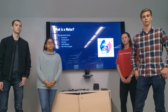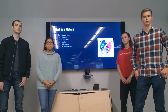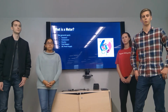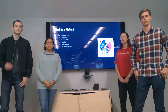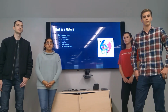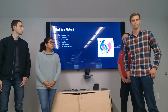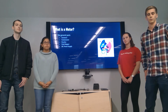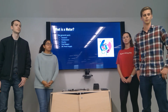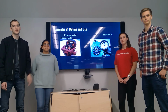The field magnets are typically, but not always, permanent magnets. A motor that uses permanent magnets will typically require less power than a motor that uses electromagnets as the field magnets. And the power supply, in the case of this motor here, is going to be a DC power supply, but some motors will actually use multi-phase AC power to power the coils. On our next slide, we're going to talk about examples of motors and uses.